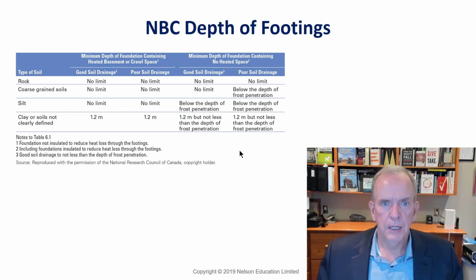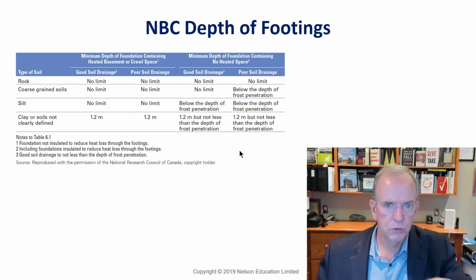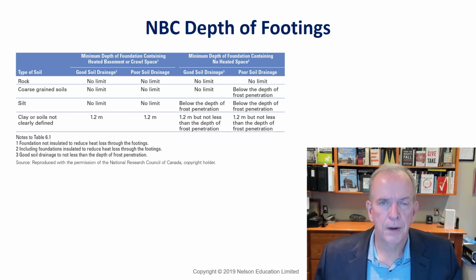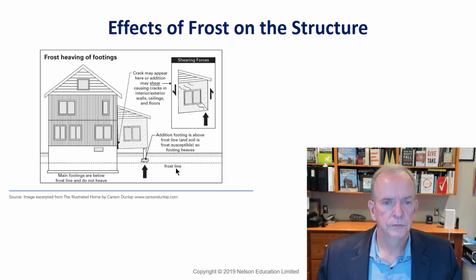In that case, then what usually is basically the Canadian Shield would be drilled. In those cases where the footings are going to go, it would be pegged, and then your footings would be formed to go along that and leveled out from that and stepped, I guess, with the rock, depending on the topography. In those cases. But typically this is where we're at, 1.2 meters.